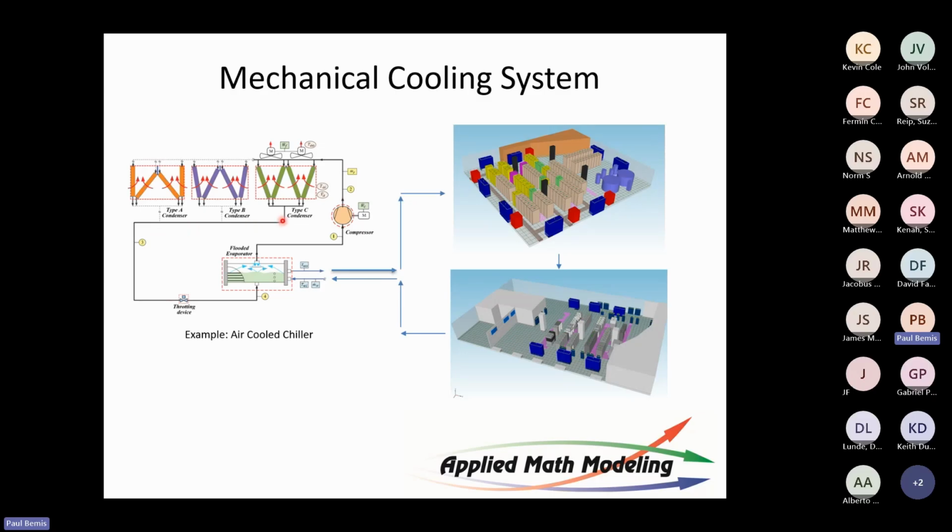So here what we're doing is using a gas, and we compress it up so it absorbs the heat, gets compressed, and then it turns, of course, because of the ideal gas law, temperature rises. You get a very high temperature up here. You also get high pressure. These heat exchangers that I was showing you just a moment ago dump to the atmosphere, throwing the heat into the atmosphere, and then it comes back around and goes through, it's a phase change in there, goes through this mixing device, throttle device, evaporator valve, and then back. So you've got ideal gas running over here, some kind of gas, and over here you've got liquid.